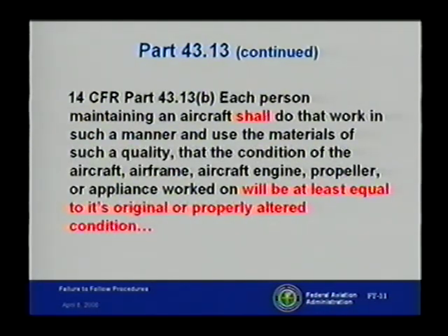Now here, where it says at least equal to, many times, and many of you may have heard the term, it's better than original. Well, if it was better than original, then it no longer meets that original. It's now been altered. And to alter anything on an aircraft, you've got to have approval for that alteration. So what we emphasize, and this is again the minimum standard, is that it is at least equal to its original or properly altered condition.